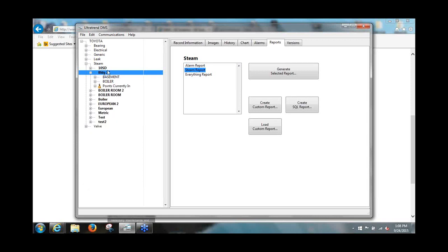At that point, we can highlight the group, upload the information, send group to probe to either the 10,000, the 9,000, or the 15,000, and send that information to the Ultraprobe so that you can go out there and start collecting data. The steam traps are a little bit different. Basically, all you have to do is make contact on the downflow side of that trap and listen for the cycle of that trap.